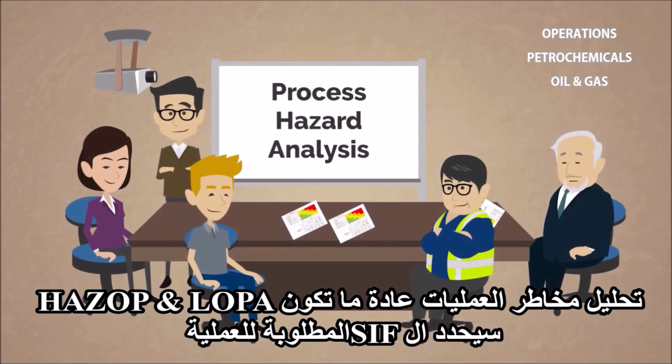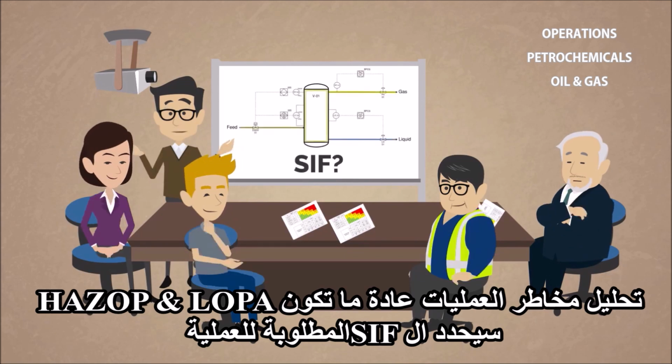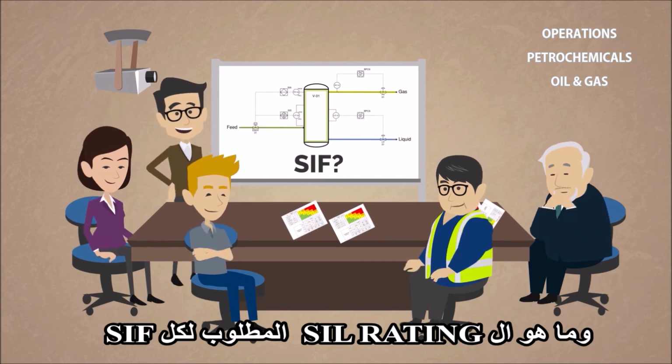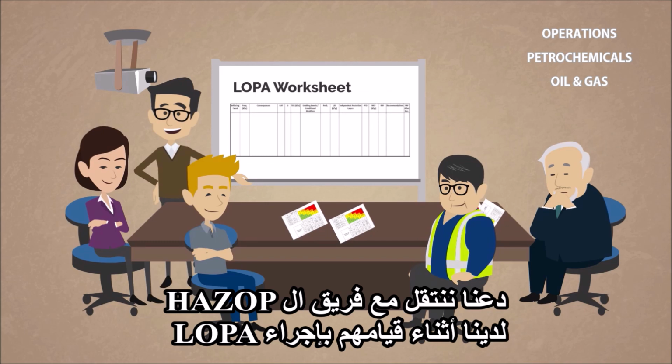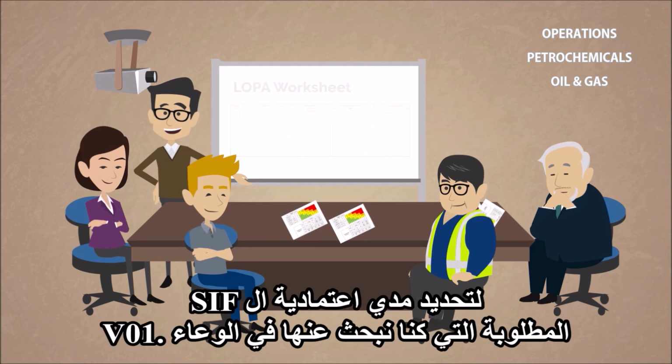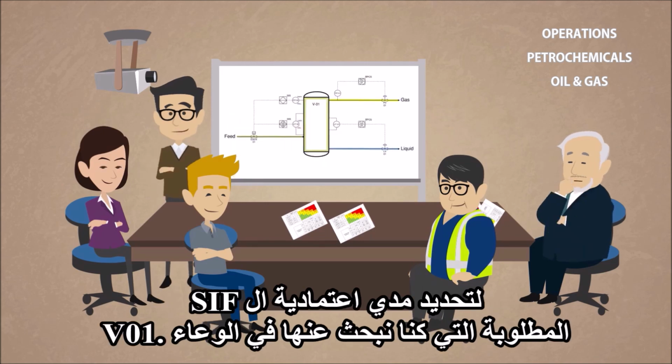The process hazard analysis, typically a HAZOP and LOPA, would identify the specific SIFs required for the process, as well as what the associated SIL rating required for each SIF is. Let's jump in with our HAZOP team as they conduct a LOPA to identify how they would determine the reliability of the SIF required for the vessel V1 we have been looking at.